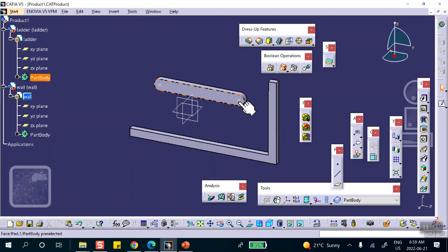Notice that when the ladder is leaning against the wall, the way I've constructed it, this point is always half an inch away from the wall. And that point is always half an inch from the horizontal wall. Now, I'm not going to worry about that because I will do a slide curve joint, which is that curve at the end slides along that line. But for this point, I'm going to do a point curve joint. So I'm going to draw a straight line here, which is half an inch from the wall. And eventually I make that point always move along that line.